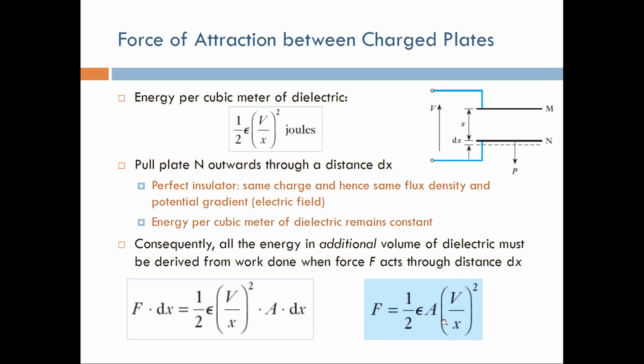So whenever you have a capacitor with a particular voltage, a particular area and a particular separation distance, you can use this equation to compute the force of attraction between the plates of the capacitor. This can be very important for capacitors holding very large voltages.